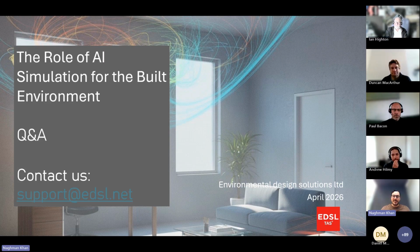We did have a technical question from Doug. This is going back to ceiling thicknesses and separate zones. How do they compare with the NCM floor-to-floor zoning rules, in the way you should do it, or how TAS does it? Pass on that one. I'm afraid my NCM knowledge is scant. Thanks, Duncan. You would model the ceiling thickness as a building element thickness. So if you had a ceiling void that was 600 mil, you'd have a building element for the ceiling that was 600 mil, and that reduces the volume of your zone, and also adjusts the surface areas, which is a good point.